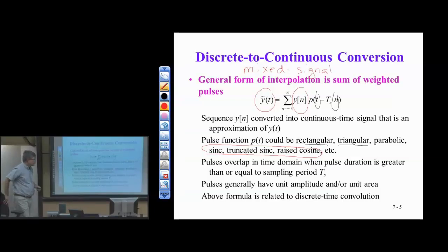Okay, so again, this is a filtering step. Each of these pulse shapes really is the impulse response of a filter. And in each case, each of these impulse responses has what frequency selectivity in the Fourier domain? Is it low pass, high pass, band pass? Low pass, right? And that comes from why? Why do we have low pass pulse shapes?